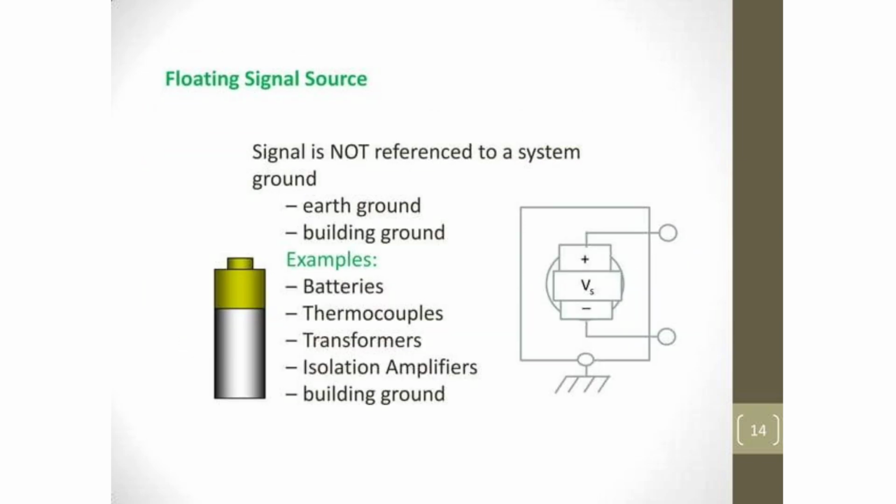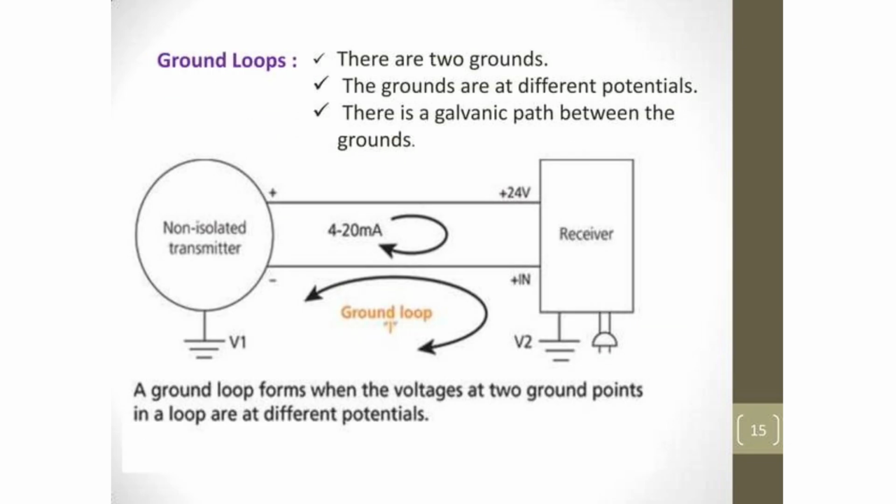Once the analog signal is properly conditioned, it reaches the ADC and the computer software system to complete its journey. The analog to digital chip takes the continuous analog voltage waveform and samples it at fixed intervals. This data is handed to the computer, and a dedicated driver provides a communication link, allowing the operating system to register the DAQ. Finally, application software built on environments like LabVIEW or MATLAB presents the information to the user interface.